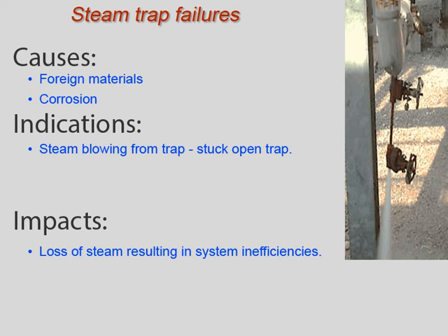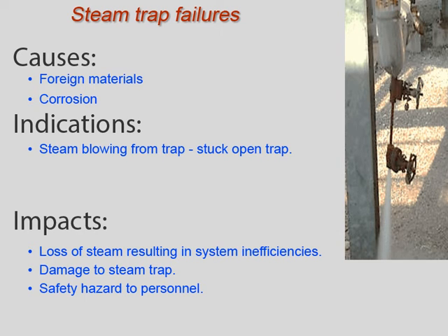Besides being a waste of steam, it can be hazardous to personnel, and continued use of a trap in this condition could cause damage to the seating surface of the valve. Exposure to live steam under pressure can cause severe burns, steam cuts, lung damage, and eye damage.